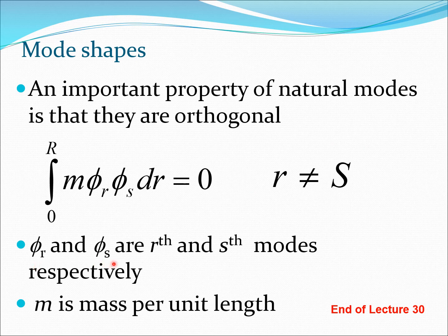And so we are going to use the mode shapes of the rotating beam or the non-rotating beam as the case may be to simplify the governing differential equation of the system and look at the normal mode equations for systems. That's something we are going to do in our next lecture when we embark on the study of response.